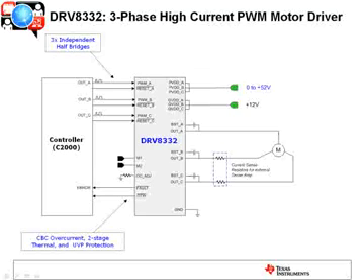In terms of protection, it's got the cycle-by-cycle overcurrent. It's not current regulation, it's an overcurrent protection. It'll cycle-by-cycle. That's for the stall and the startup currents. It does have a 2-stage thermal protection, so at 125 degrees that OTW is going to go low, let the controller know that it's getting hot, and it'll shut down and send a fault if you cross 150 degrees. And it does have also the built-in undervoltage protection.